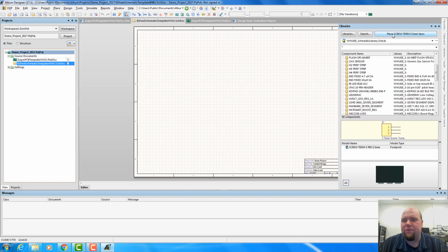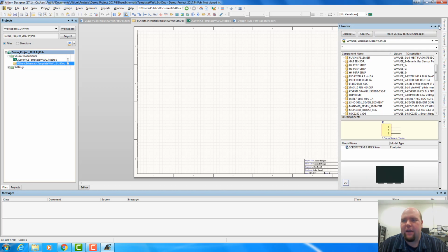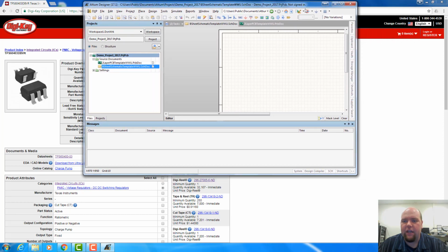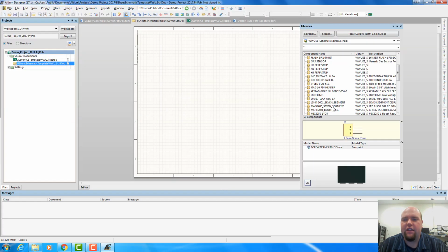What happens if we're looking at these libraries here, and let's say we accidentally click the X, and we made it go away? Whenever we lose the library or the vault tab, we can always get them back. If we go down to these little menu items down here, we can go to System, Libraries, and that'll bring us back that library panel, so it's not lost forever.